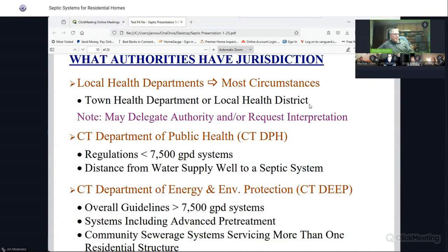Well, yeah, salt and concrete don't mix. It's a disinfectant, so it retards the bacterial action. And because it's soluble, it leaves the tank with the water and crystallizes out in the fields. Those are all good reasons not to do it, but we see it anyway. Yeah, you see it, but it's not legal these days to do that. You have to have a separate system. Like I said, I'll be talking about those separate systems here.